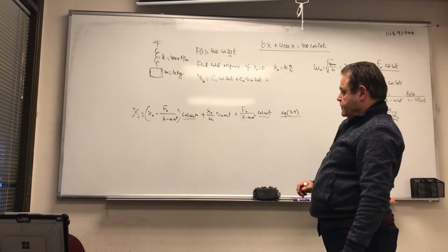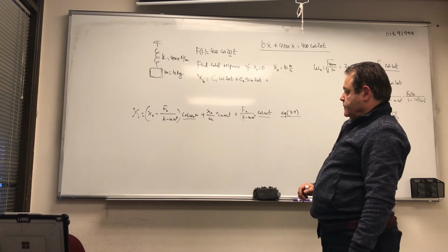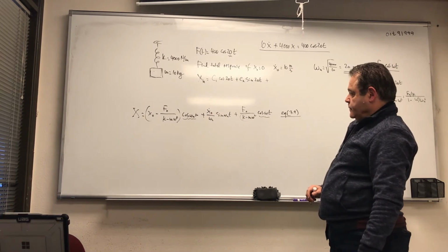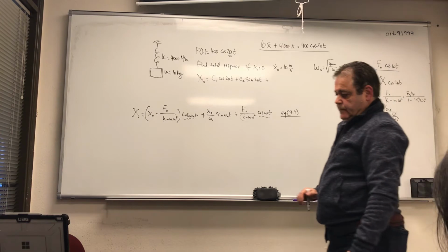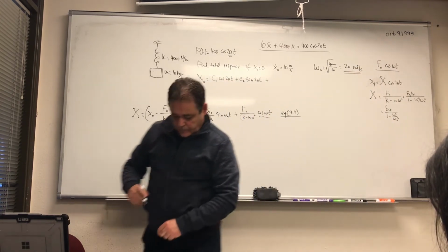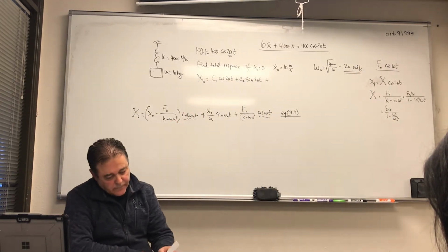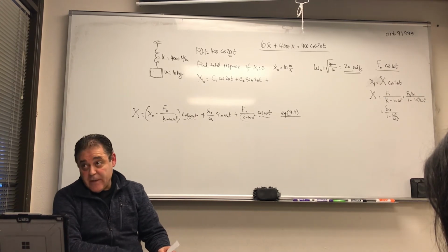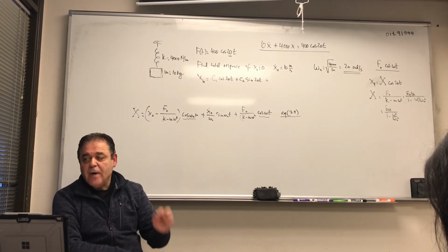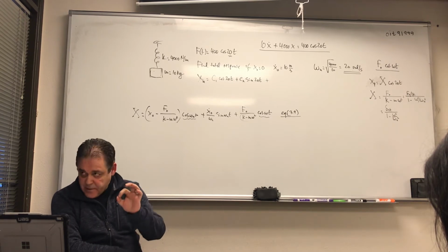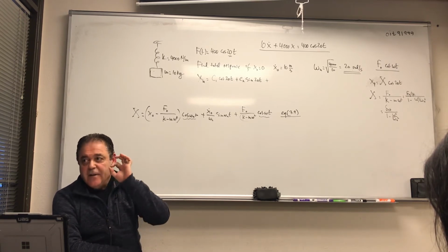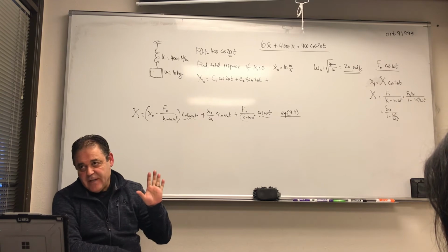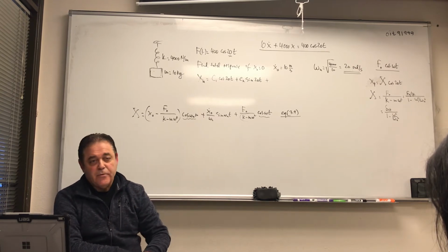When it's equal to 1, and they get down to the equation on page 266, 3.15, after they apply L'Hopital's rule, it says, thus the response of the system at resonance. And resonance means when it's at 1, right? When omega over omega n is equal to 1. So anytime you have resonance, we use equation 3.15. You use that equation, and you don't need to go back and redo all the situation.